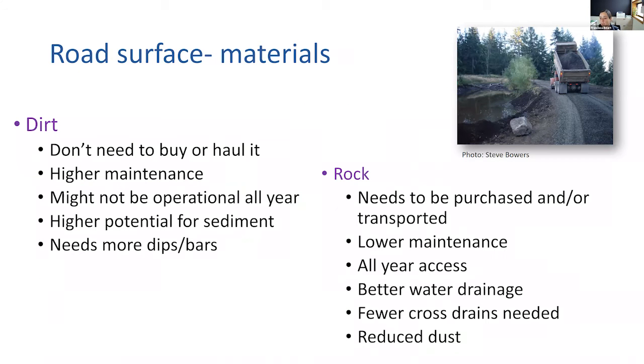So here's a comparison between dirt and rock roads. What I call dirt roads are the ones that don't have any rock in it. The good thing about those is that you don't need to buy or haul the rock. However, they do have higher maintenance, right? The rock is pretty much what it's doing is draining that water. So it's keeping the surface dry. And for that reason, it makes it better in terms of lower maintenance.